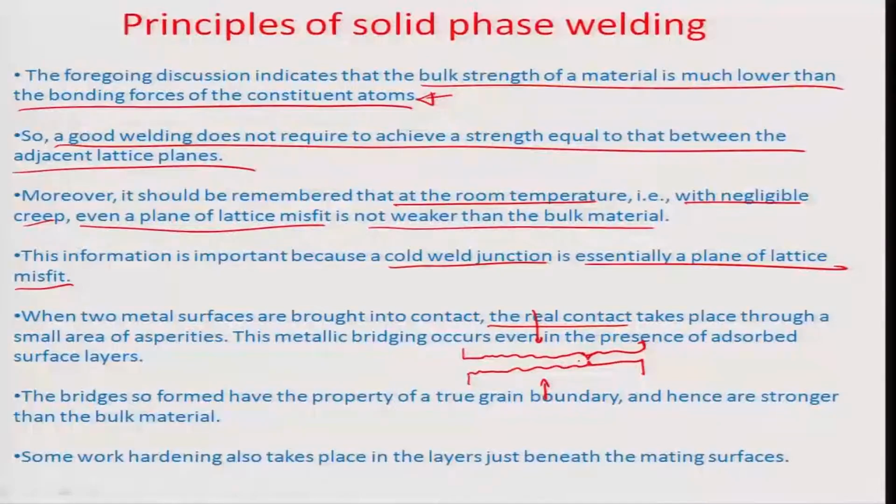So, when the surfaces join each other, obviously the real area is, as I had mentioned earlier in the study of friction, much smaller. So the A real is smaller in comparison to the A apparent. The apparent area is that of the surface, and the real area is very small. So, in this region it is very easy for the overall stress to reach the plastic deformation